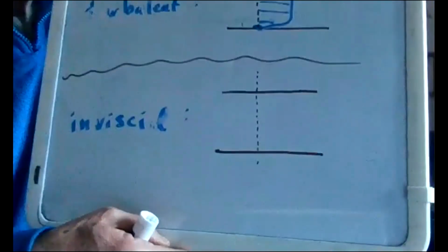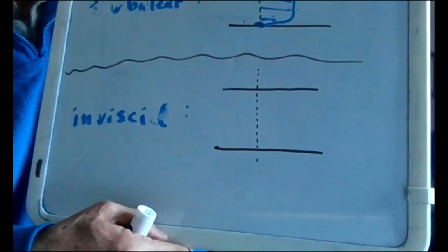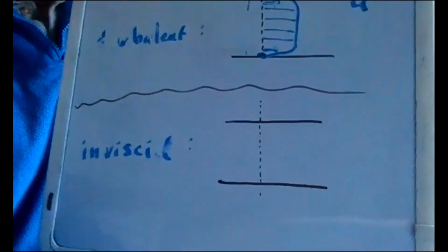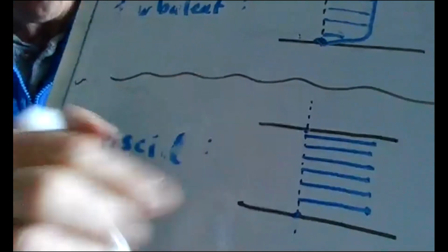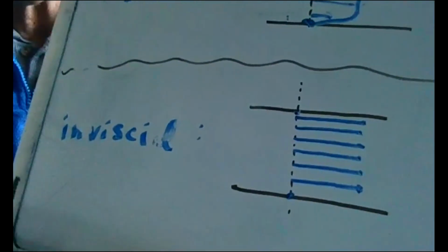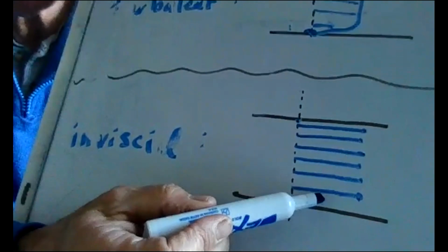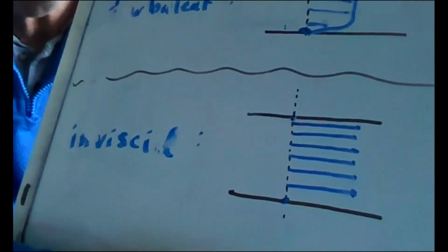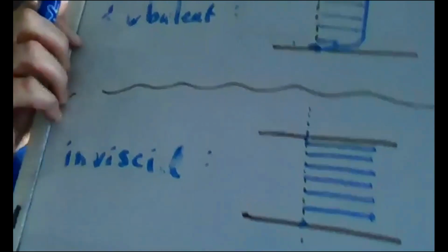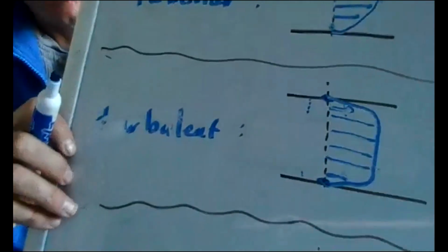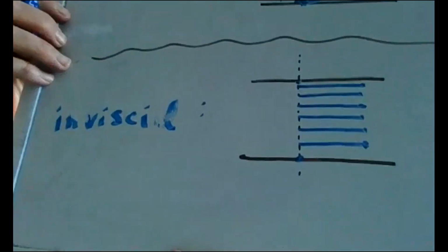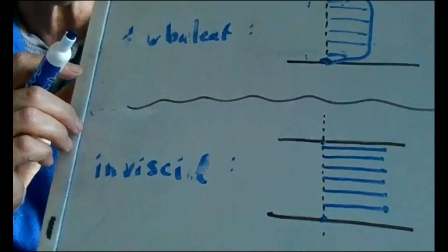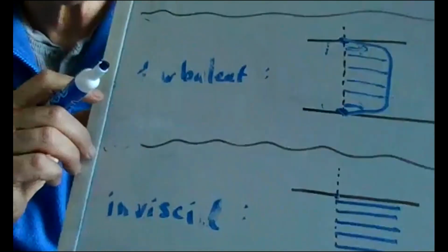All right, one to go. Go ahead and get the velocity profile for inviscid flow. Yep, that's it. We can think of there being a no-slip condition at the wall, but there's essentially no viscosity, so there's no effect. So we end up just having a uniform profile like that. It's kind of interesting to think about: is the turbulent profile closer to the laminar or closer to the inviscid? The turbulent profile is closer to the inviscid. There are viscous effects at the wall, but in the middle it kind of gets free from viscosity, and we end up having something like a uniform profile.